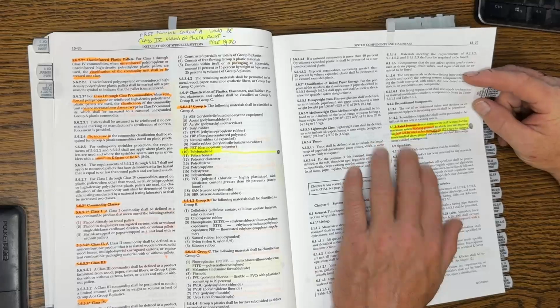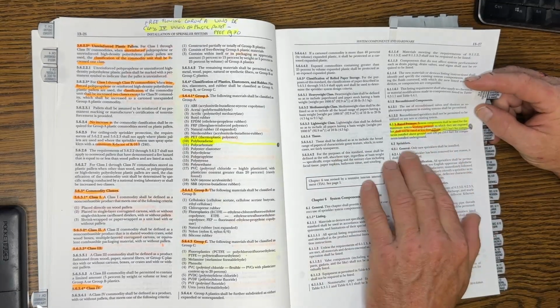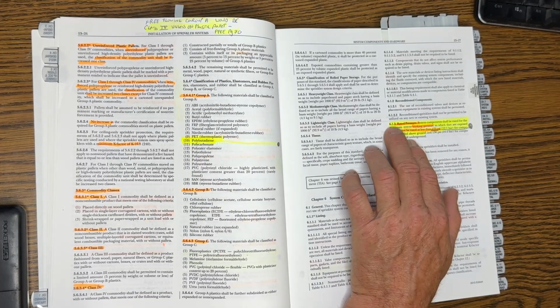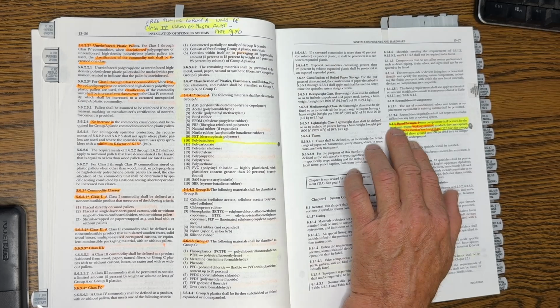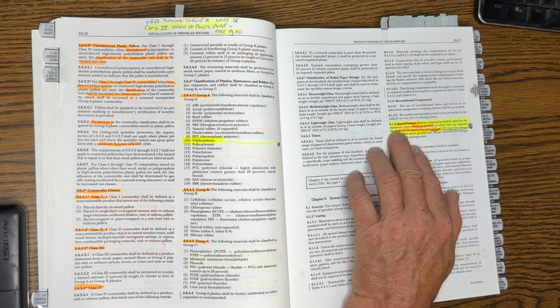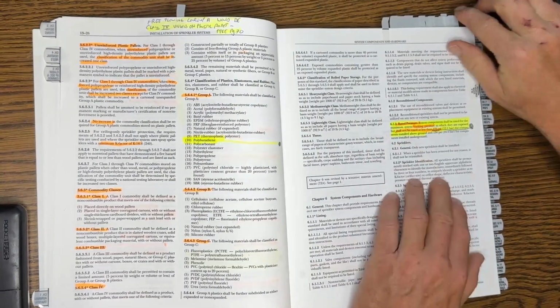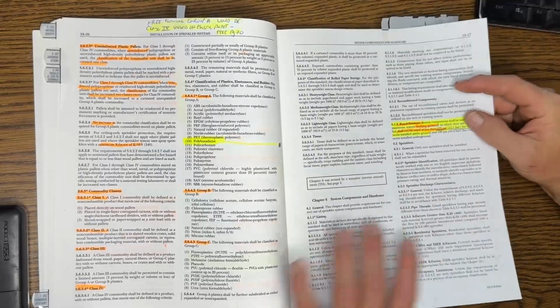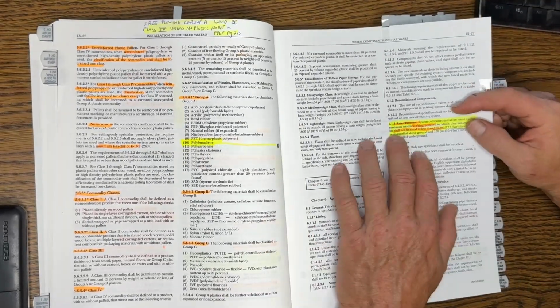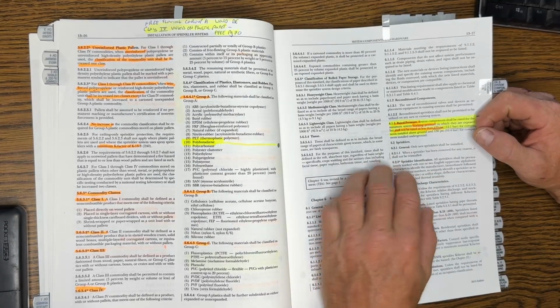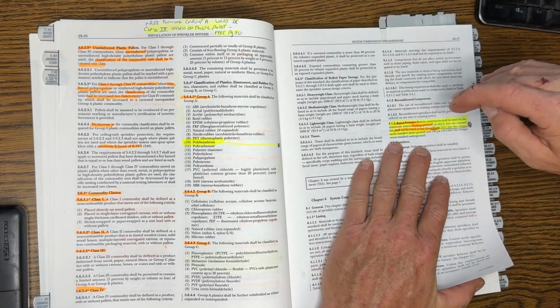Okay, next one. Let's see. We are at 613. I'm going to read the question to you from the quiz just for the heck of it. Let's read the question so we can see what it says. 613. Bear with me, folks. What's the minimum pressure that sprinkler system components shall be rated to? A lot of times, this will throw you, folks. When you're designing a system, it's designed on a head at 7 psi. The way they've worded this is tricky.